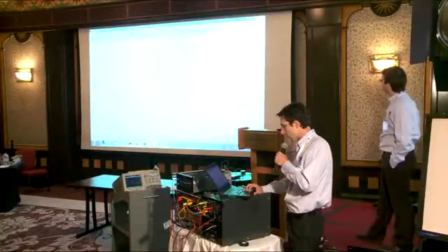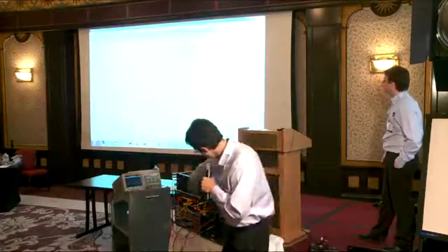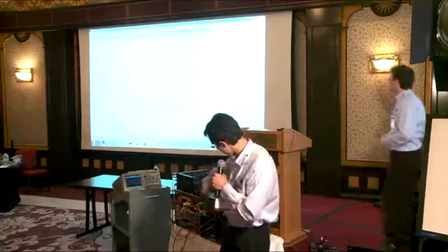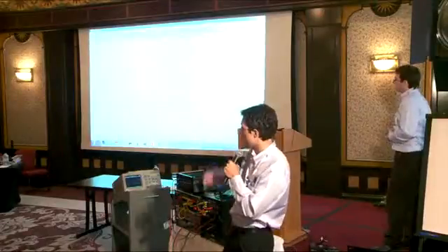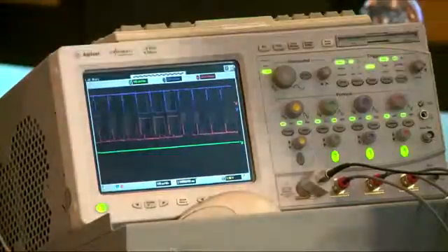So now what we have here, we have a duty cycle going out of the simulator. So this is what I'm measuring. I'm sending to the IGBT. So I'm currently sending this pulse pattern here on the output, which is a sine wave. So we should be able to generate a sine wave out of the simulator. So now, next thing that we might want to do is to see what's happening for real on the real system. So I know that I'm sending my firing pulses to this guy here.